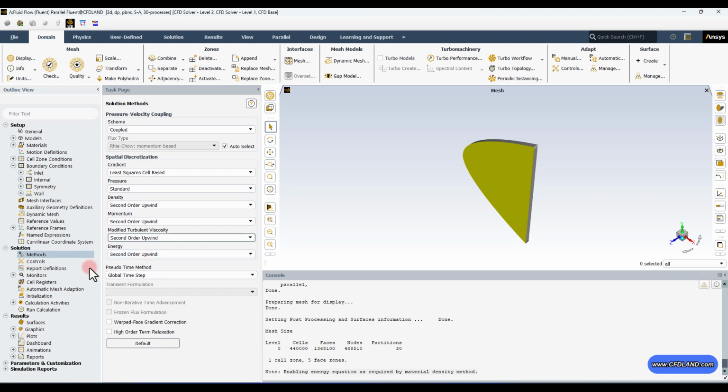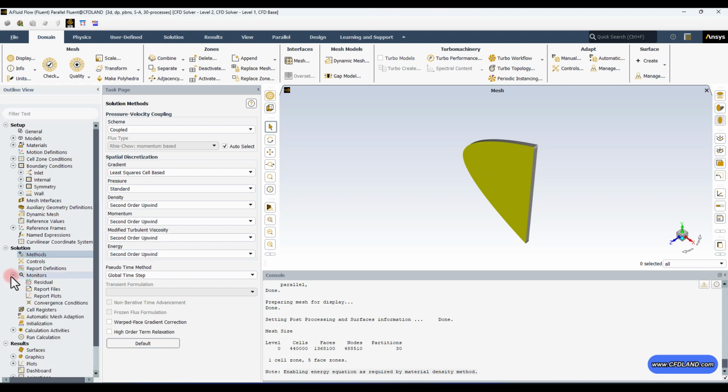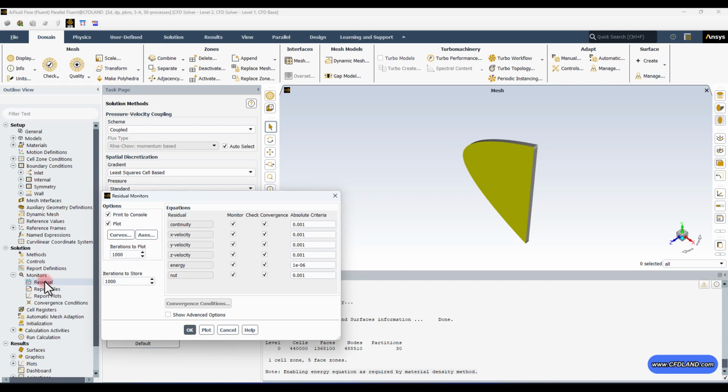Very well. So it's time for checking our convergence criteria. On most of the simulations, the residuals are known as the primary convergence criteria. Actually, in CFD simulations, these are numerical measures of the imbalance or error in the conservation equations, and for each cell it is computed and reported in the console part during the simulation. But it may not actually be a guarantee of our convergence.